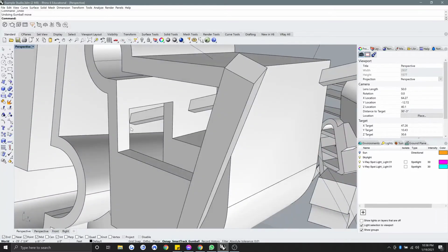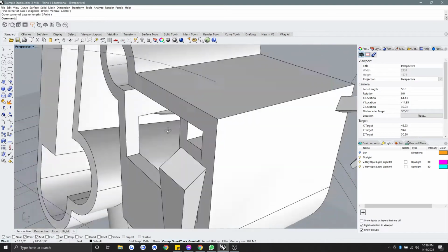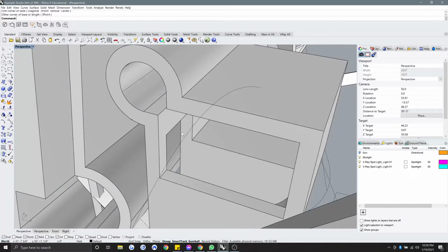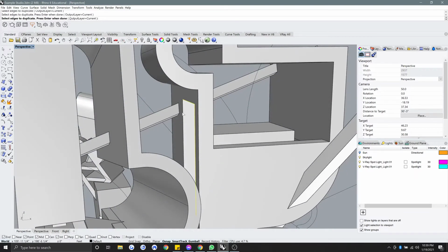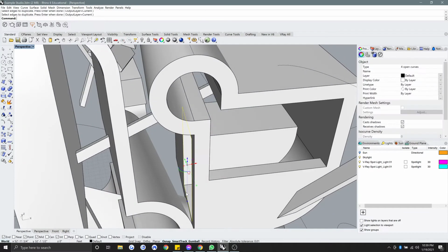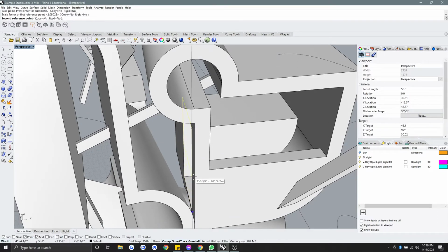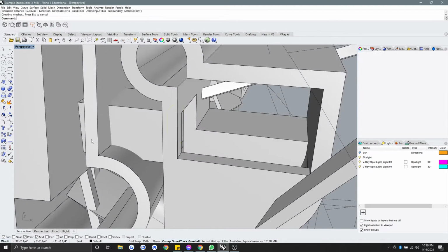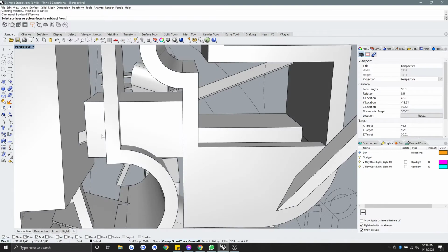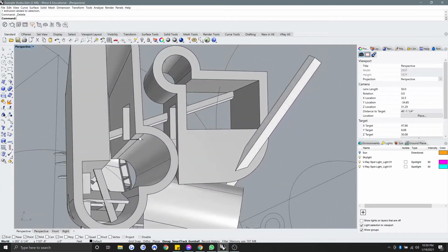This also has like this projection here, so that might make me think that to get from one of these sides to the other, dupe edge, I would need another kind of aperture like I had before. So I'll join those edges, scale, maybe make it smaller. Maybe you enter on the top half of this one, and it would extrude through here. So I'll Boolean difference from this guy, and then delete that. So now there's a visual connection between those two on the interior.